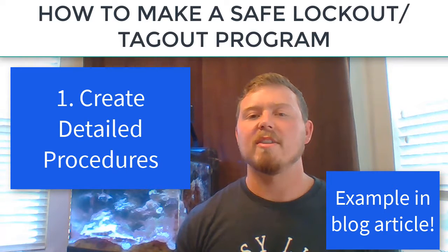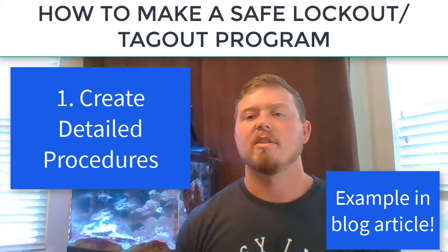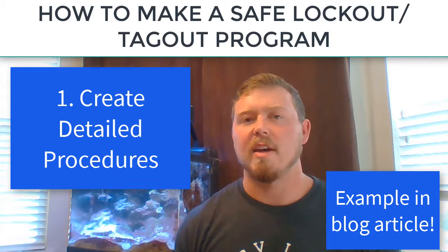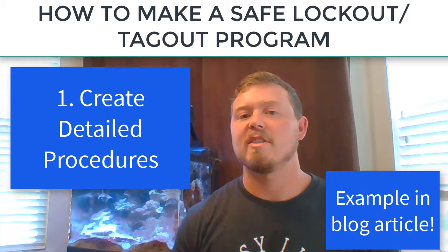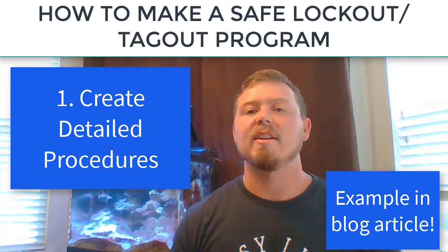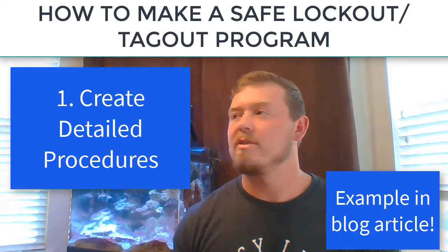Be sure to include the device used to lock out the energy and the method used to verify it is locked out in this step. This procedure should also include how to bring the machine back online in the same step-by-step process and include exactly how each step should be performed in the safest way possible.